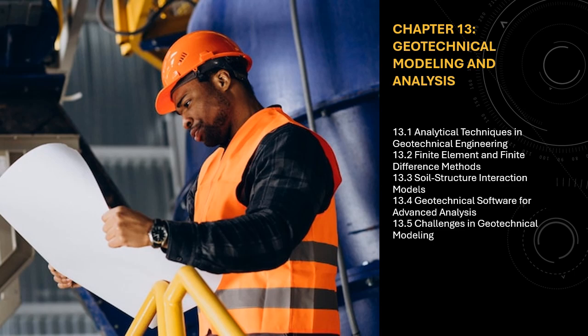13.5.4 Uncertainty in input parameters. Geotechnical modeling is heavily dependent on accurate input parameters, such as soil properties, e.g., shear strength, modulus of elasticity, permeability, which are often obtained through laboratory testing and site investigation. However, these parameters are subject to significant uncertainty due to inherent variability in soil properties, limitations of testing methods, and the quality of available data.